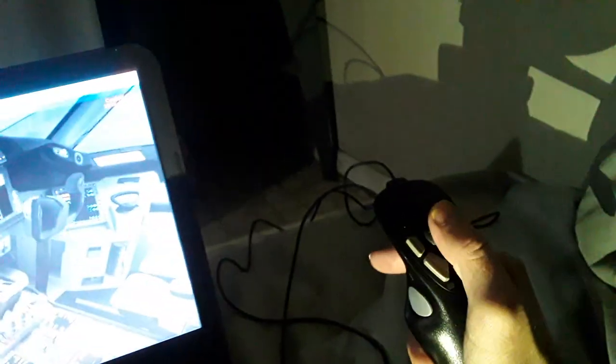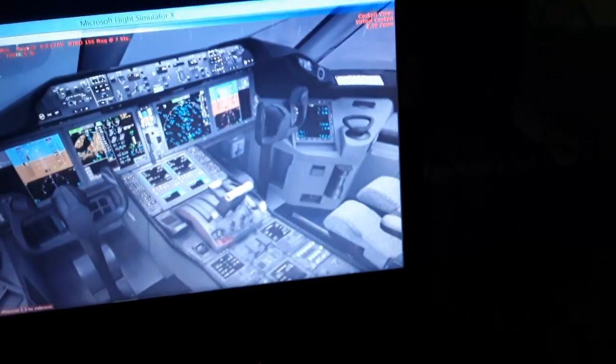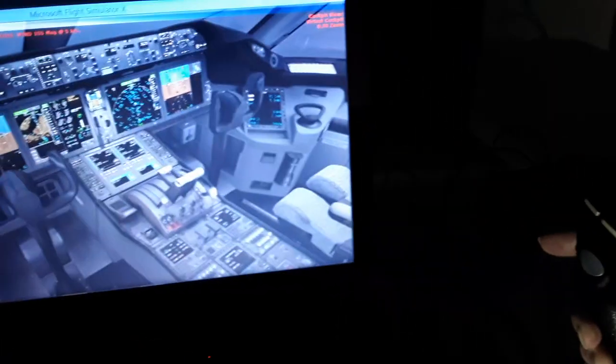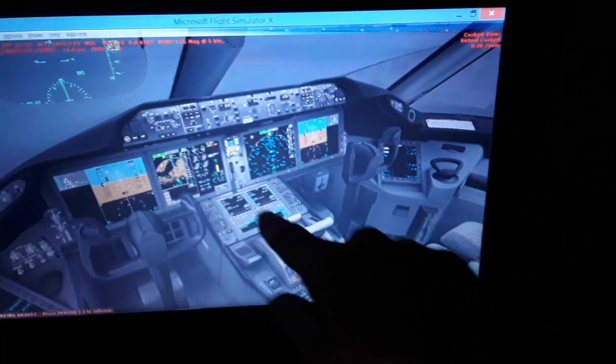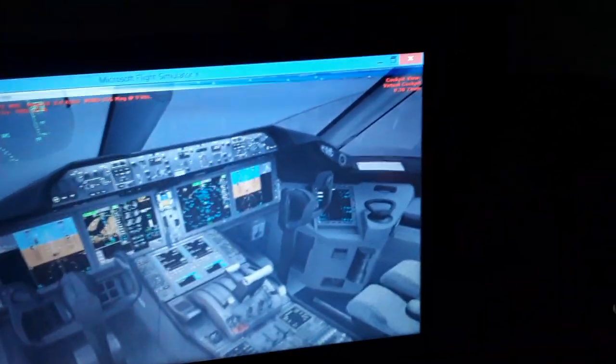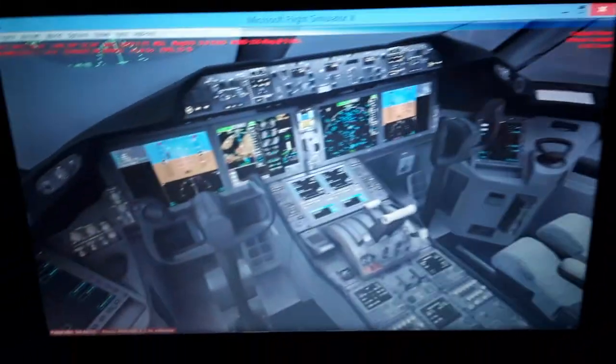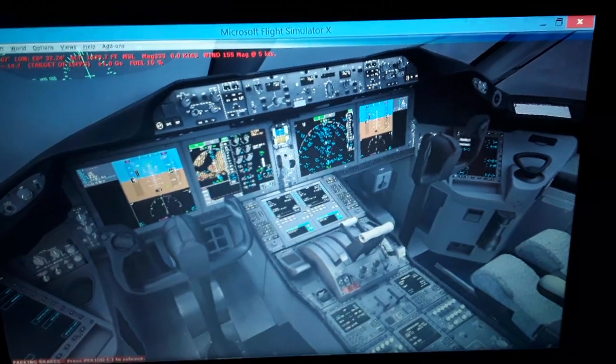So the hydraulic fluid tanks: all flight control movement you see is from hydraulic fluid actuators in the flight control surfaces. Also we need pressurization from the engines to make movement: landing gear extend and retract, thrust reverser for the engine, the nose wheel steering, the rudder pedals over here. The rudder, all flight controls need hydraulic fluid pressurization to move.